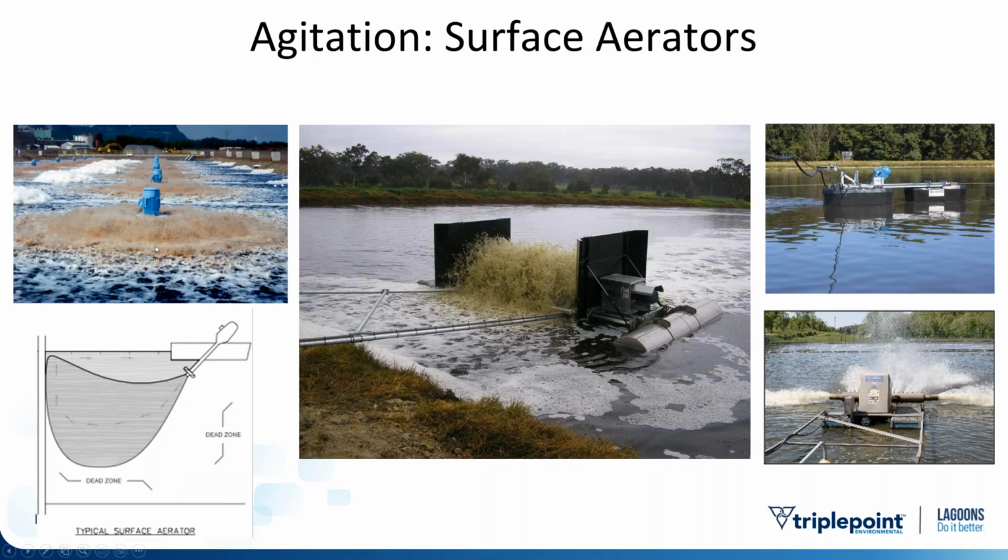Mechanical looks like this. The idea is we're going to move the water, throw it around to create surface area, create that air-water interface such that the oxygen can be transferred. And it's done in various ways. Surface splashers, aspirators, turbo units. This looks like a house brush aerator.